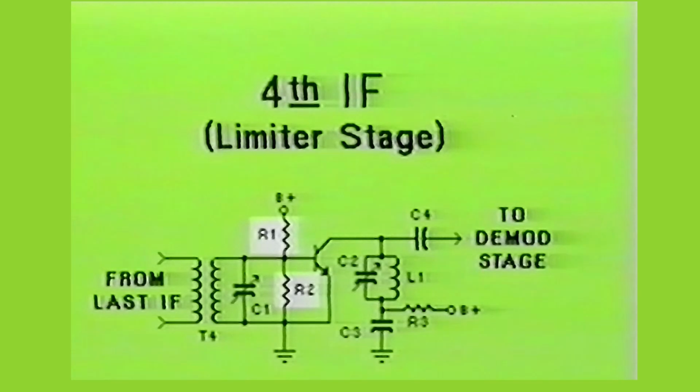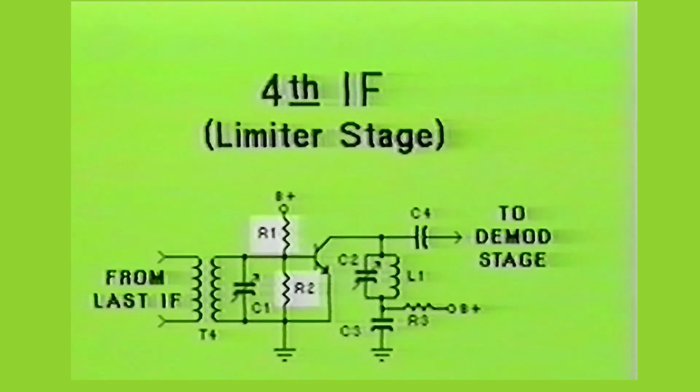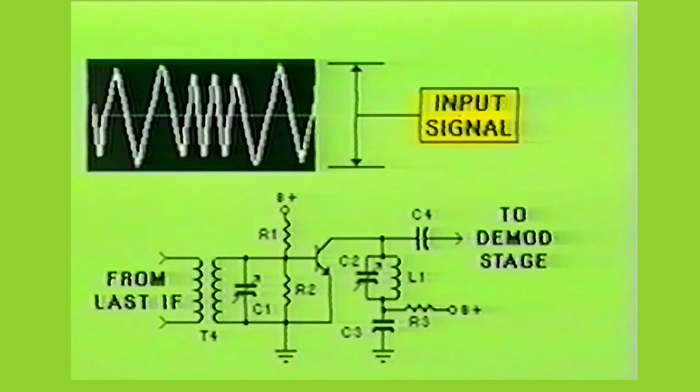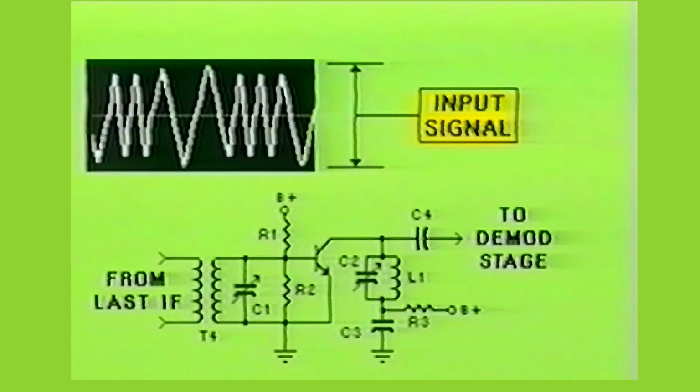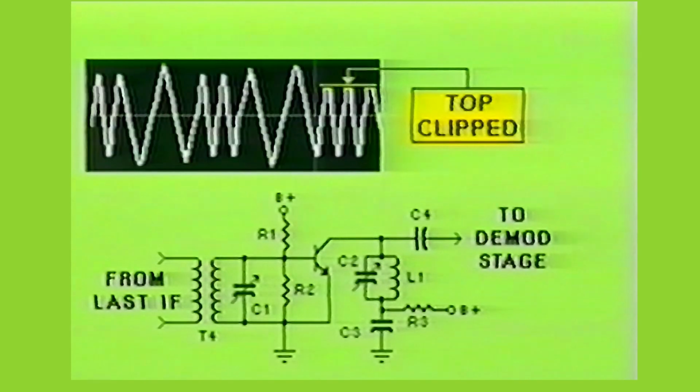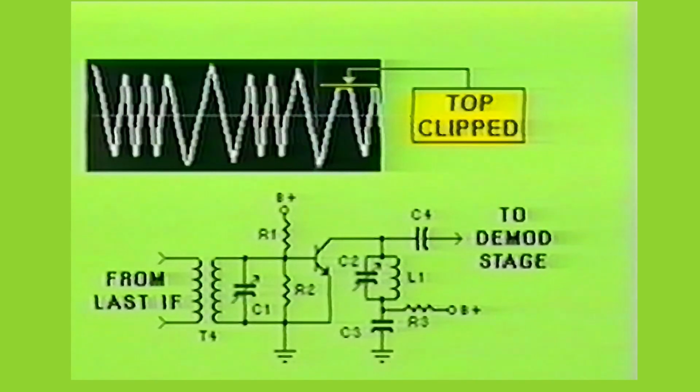Resistors R1 and R2 are chosen so that the forward bias across the emitter-base junction of the transistor is very low. Since the threshold of the transistor is low, it does not require much of a negative going signal to cause the transistor to go into cutoff. When the transistor is in its cutoff region, its collector voltage will reach its maximum level, even though the signal driving the base will go even further negative. Since the current through the transistor cannot decrease below its cutoff point, the top of the voltage waveform at the output will become clipped.